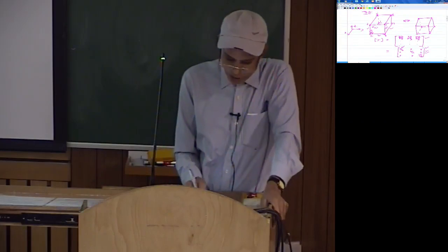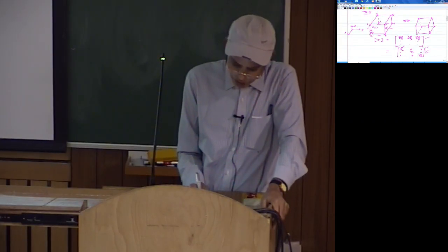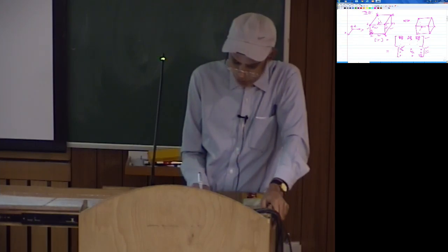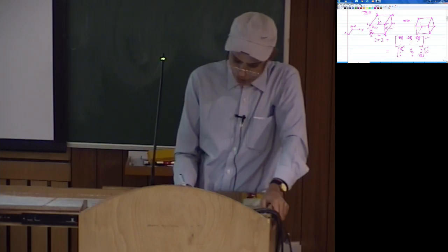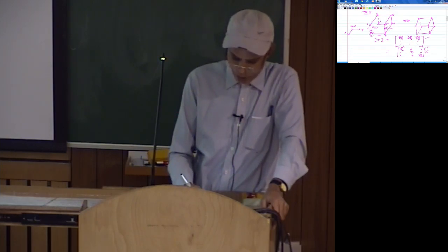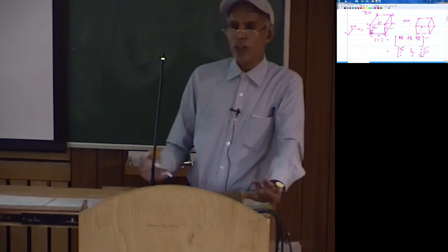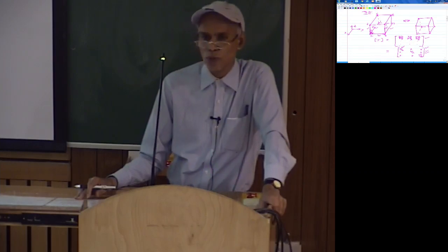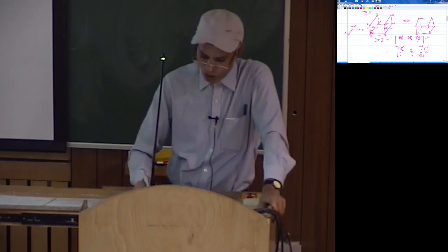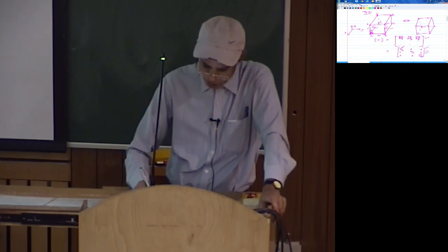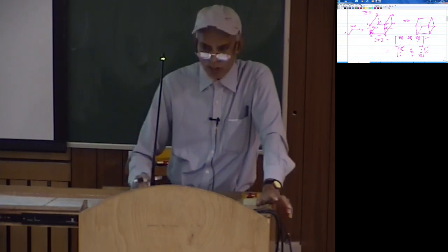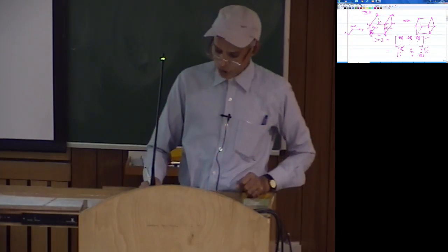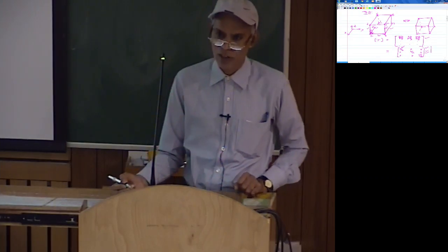So for that reason, similar arguments apply here: the included angles also individually, if I look at this face, the angle between this edge and this edge, or between this edge and this edge, similarly the angle between this edge and this edge, they all should again be similar to what we discussed for 2D, that is, should lie between 45 to 135. So that the Jacobian is properly conditioned and it is not introducing too much error if you are using the same order of integration that you would otherwise use if the Jacobian is constant.